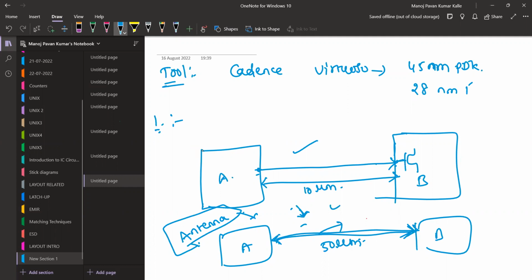And sometimes a signal carries more current and is not only going to the gate, it is going to some source and drain junctions, where there is more current, around 1 ampere or something. Then the basic criterion you have to consider is that you should route this signal with sufficient metal width.